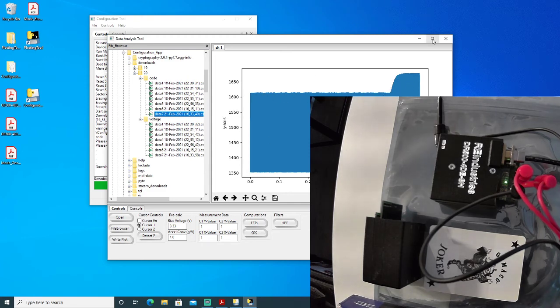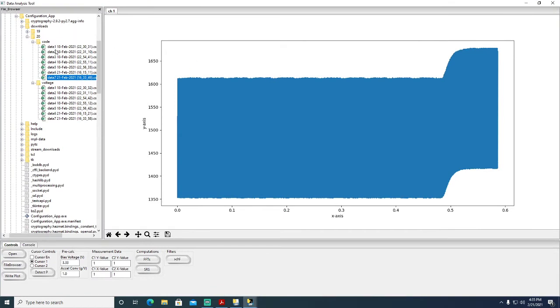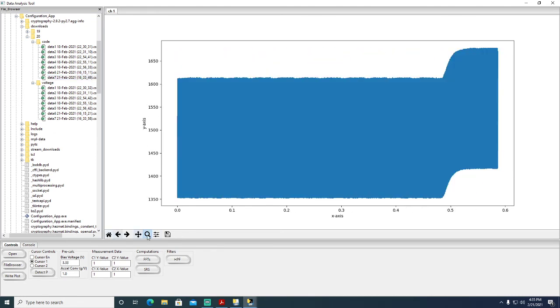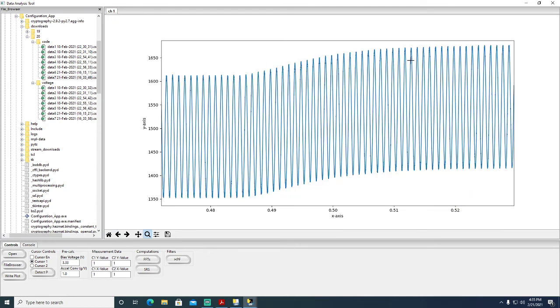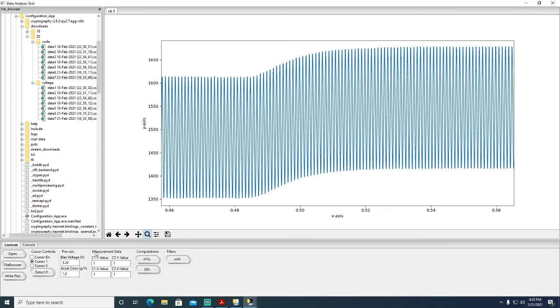Now if we can turn our data recorder webcam off, we can make this bigger and zoom in to some of this information here. So we'll look at our waveform. There's our sine waves, and we'll look at our transition event. Okay, and then we can also look a little closer here, put our cursors on, and see if we can find our threshold violation.